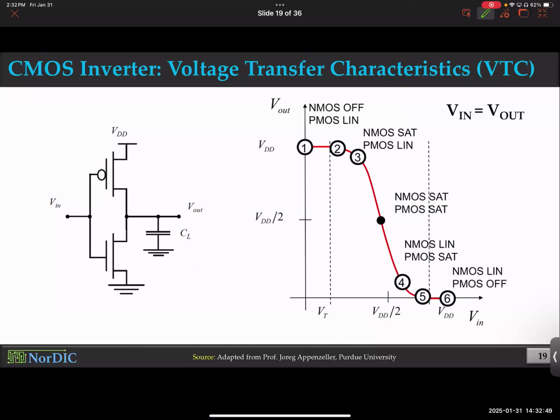So it's not easy when you put two transistors, NMOS and PMOS, together, because their VGS and VDS are changing simultaneously. Here is how. Let me show you. So this is your output. When the capacitor charges up or discharges, this node voltage changes. Would you agree? This is drain for the NMOS. Whenever this output changes, your drain to source voltage changes. At the same time, you're changing the input from low to high or high to low.